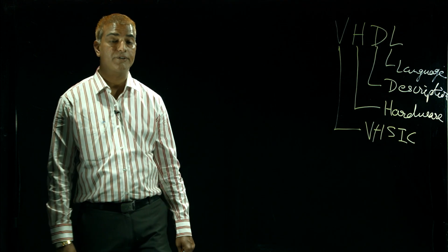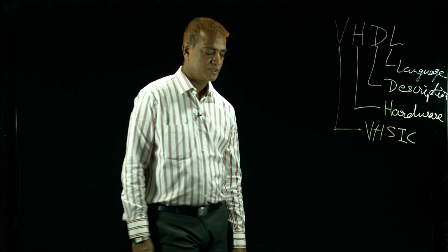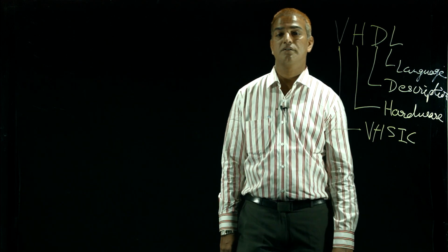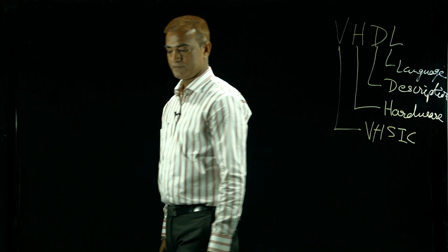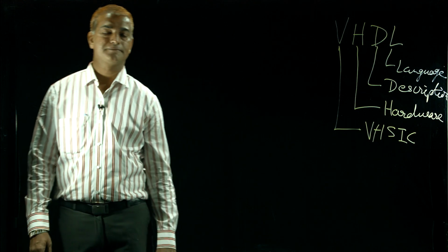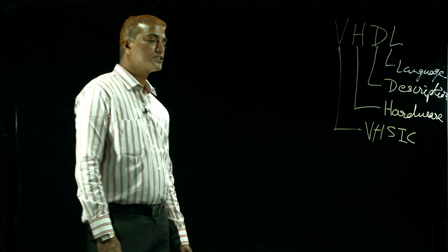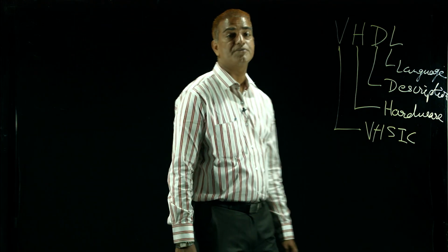And the last design unit is the package body. The package declaration works in correlation with the package body, and this package body works similar to the architecture body, which we have already seen.